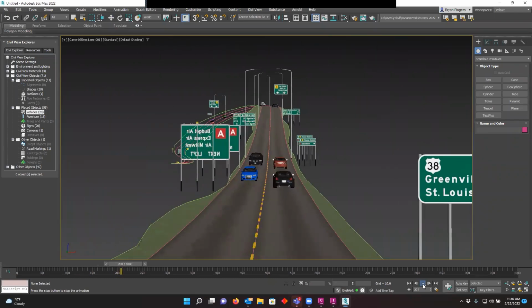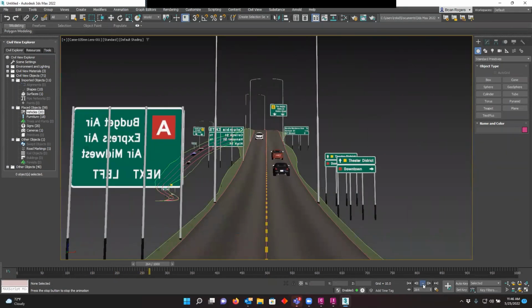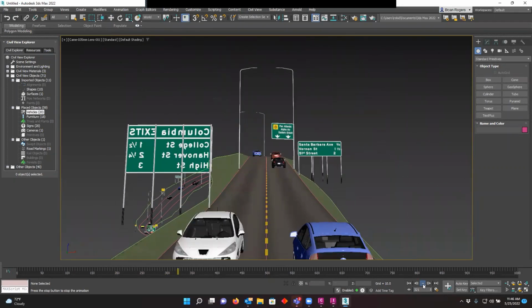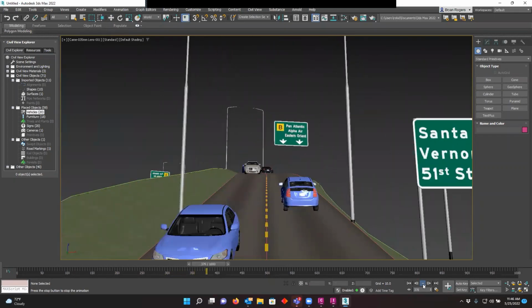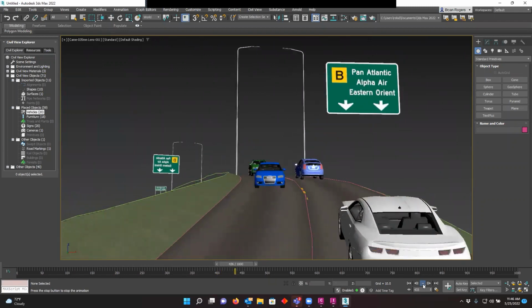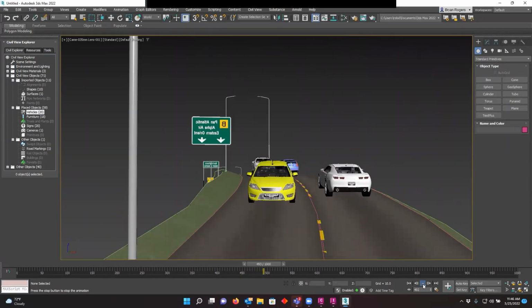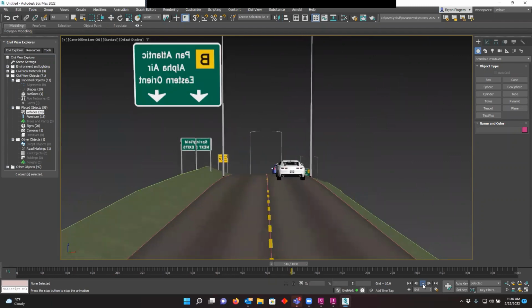You'll see the cars are pretty smooth because we did set that interval at 1 foot on the feature line. Now, if you didn't do that, that car would look like it's got hydraulics and be riding a low rider up and down the street, right?